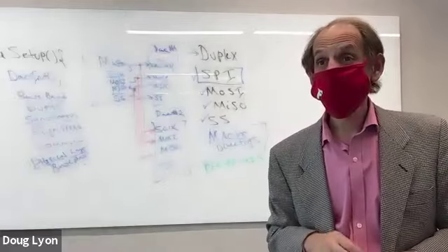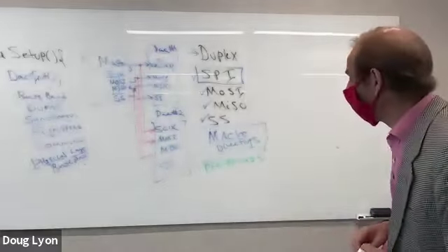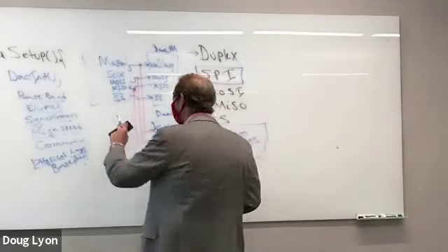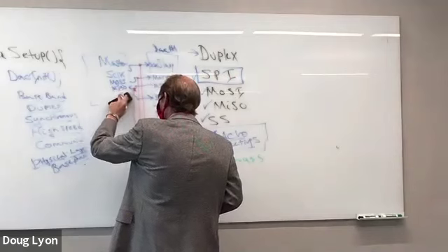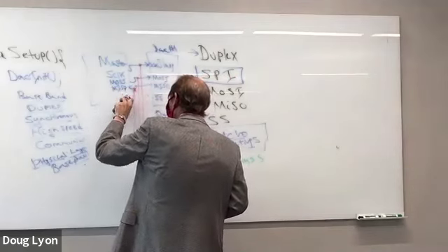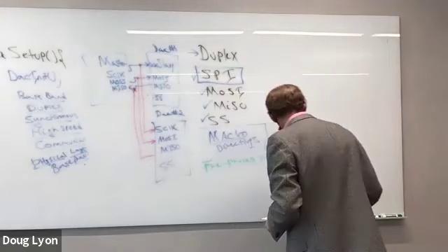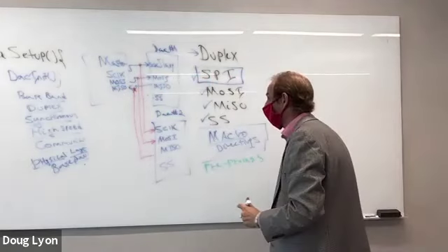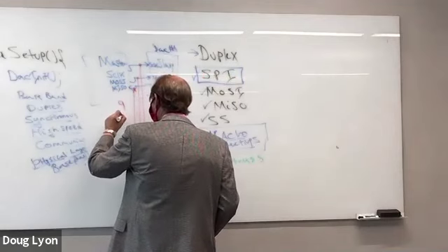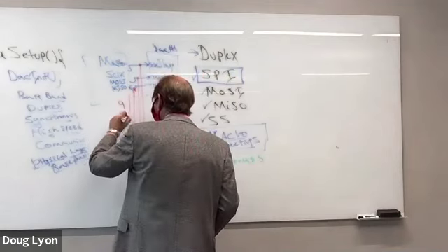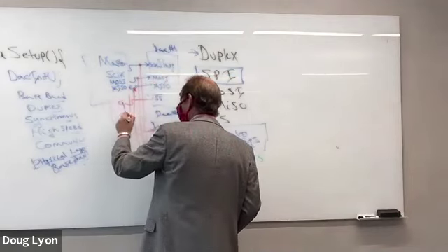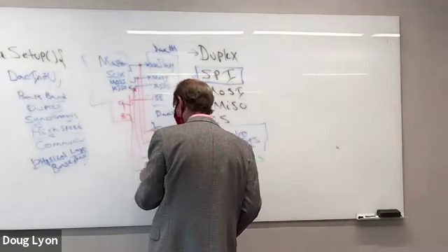Yes, sir. Use an encoder or decoder? Yeah, use a decoder, right? So if I have a decoder, then what I'll do is, and I don't even need a decoder, right? Because I've got an Arduino and it's got a bunch of I/O ports. So if my I/O ports are available, I can use my I/O ports. I can use pin 9 and pin 8 on my Arduino, and I can make it so that pin 9 chooses this device and pin 8 chooses that device.